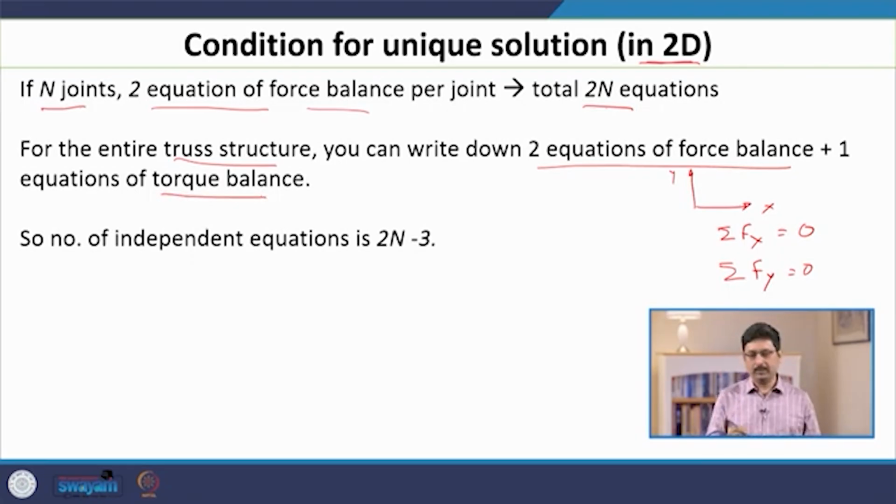Remember the definition of torque. If all the forces are acting in the same plane, the torque is a cross product of the location of the line of action of the force with respect to the pivot point and the force itself. So, the moment of the force is going to be perpendicular, in the direction normal to the plane. So, you have only one component of moment; it is a simple situation.